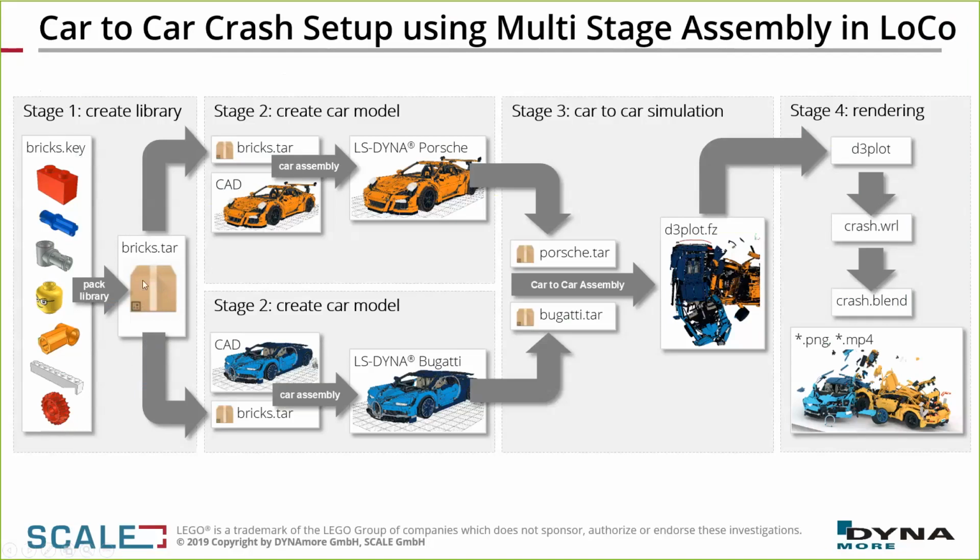And then in my second stage, I just created a simulation, importing and linking the file with the meshed bricks into the real car CAD data, and with the script earlier mentioned, I created the LS-DYNA simulation file for the Porsche model.